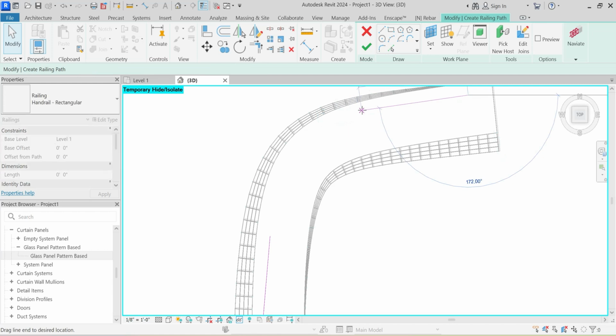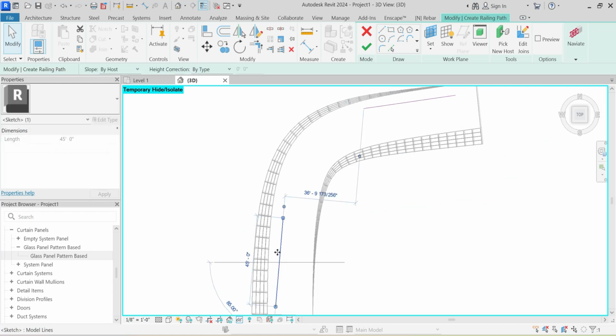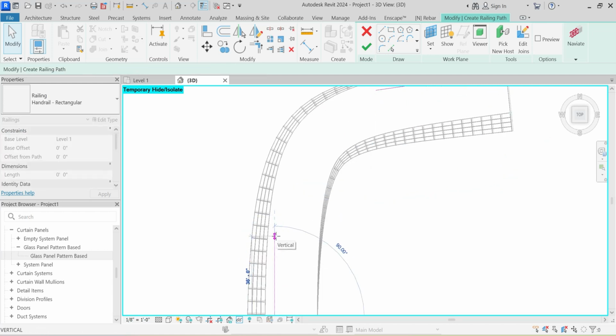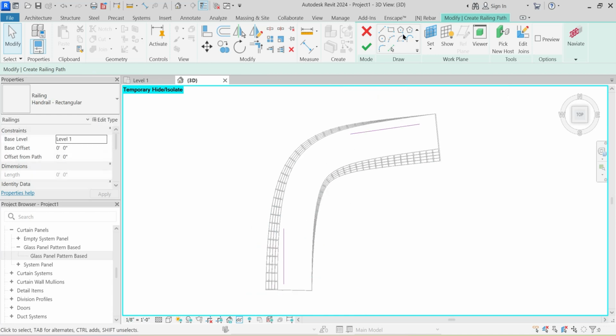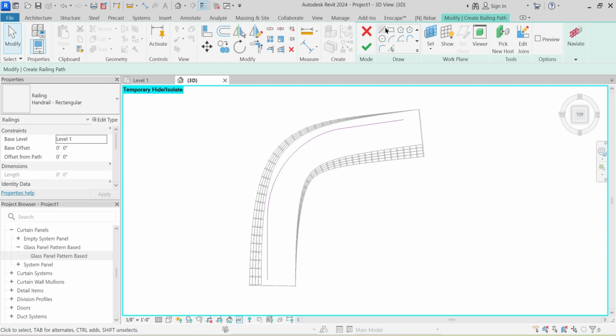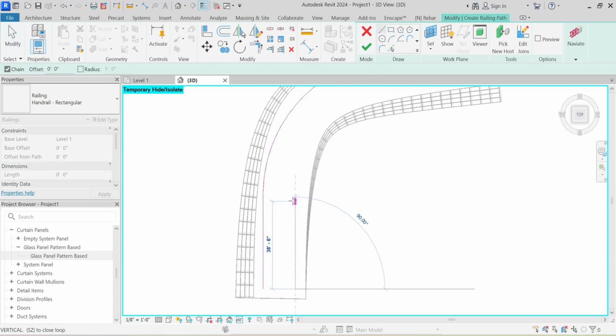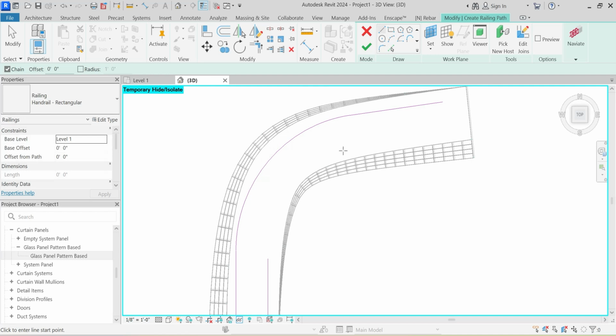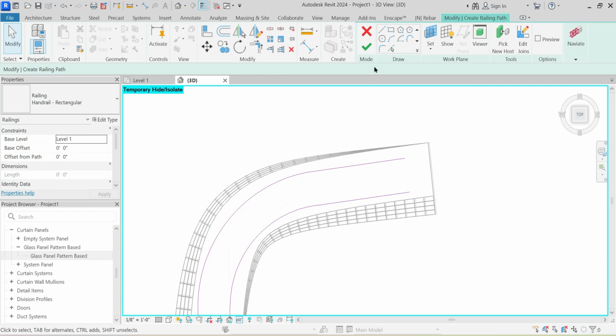You can have this entirely as a curve, wherein I'm just going to say fillet 1 to 2. And one more part: create this to this. One more line from here to here, and fillet that as well, 1 to 2. Something that matches.